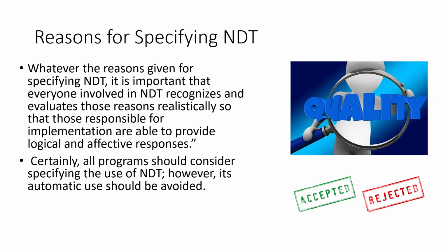Odds are, if you're welding or manufacturing something, you're going to have some type of non-destructive testing. And probably the baseline is going to be visual testing, but if we've got radiography or something that's expensive, we shouldn't just automatically use it unless we have to, just due to the expense. And especially if it's all welds need to be x-rayed. Well, what if it's a handrail? Do we really need to take the time and money to x-ray a handrail? Probably not. So some of these costs can be avoided. We'll talk about some of this stuff.